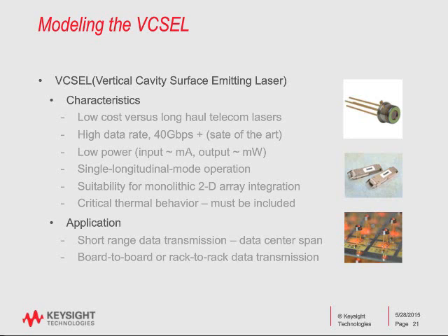We need to be able to describe the electrical to optical transfer characteristic correctly. And one thing about VCSELs, as anyone who's worked with them will know, is that they have a critical thermal behavior, and any modeling that we do has to definitely include that. And for the application, data transmission in the data center, any modeling that we do typically would need to be useful in that context, with the ability to do simulation.